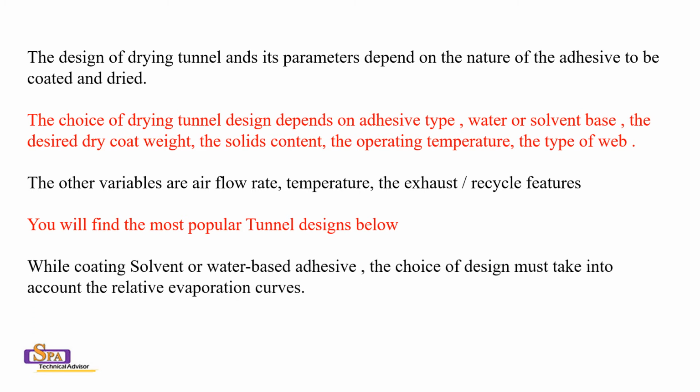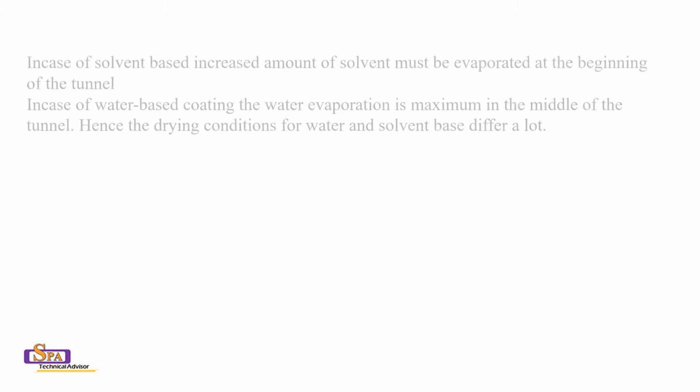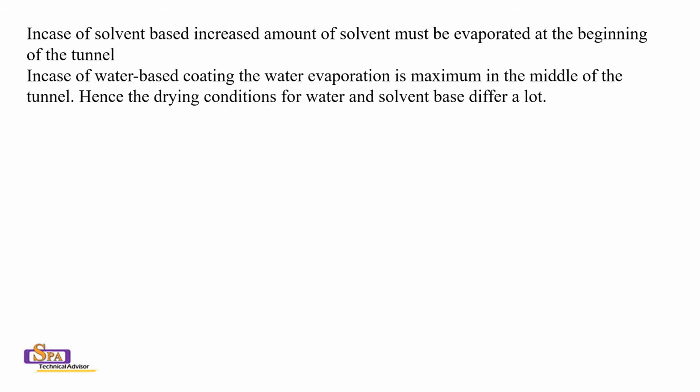While coating solvent or water-based adhesive, the choice of design must take into account the relative evaporation curve. In case of solvent base, an increased amount of solvent must be evaporated at the beginning of the tunnel. In case of water-based coating, the water evaporation is maximum in the middle of the tunnel.